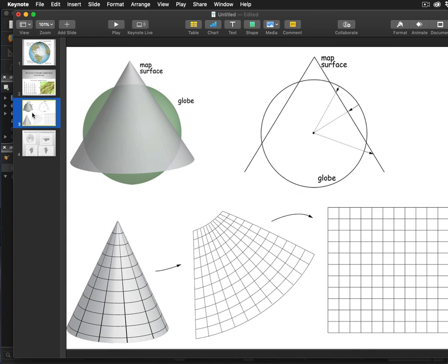There's a process to go from this curved surface, and the points of things on this curved surface, onto a map, and it involves some distortion. So for a conic map projection, we project from the surface of the Earth down onto a cone, and this is our latitude and longitude grid on the cone. Then we mathematically slice, unroll, and stretch out the cone, and you can see we get some distortion up here near the north.